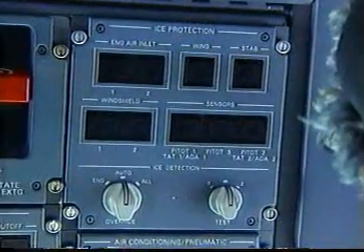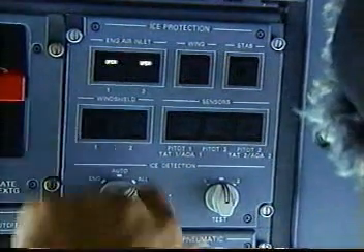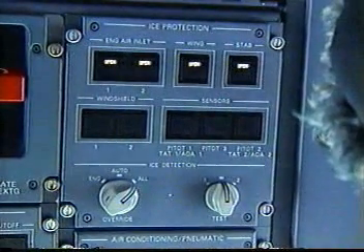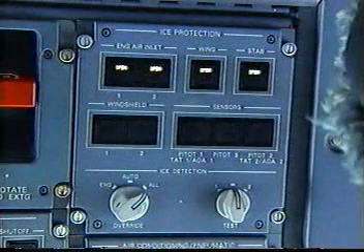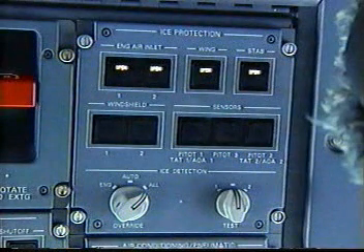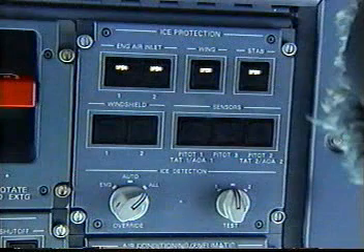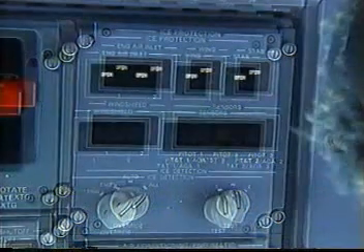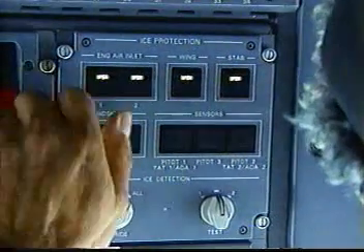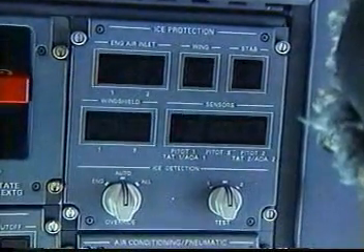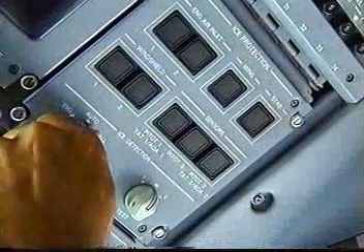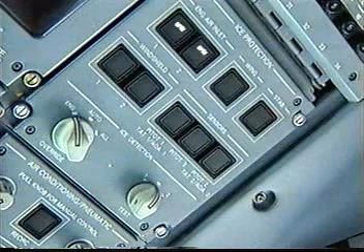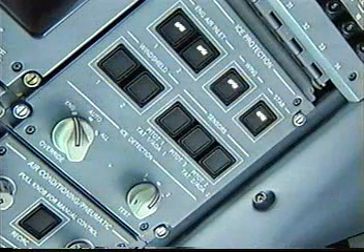The override switch, when selected to all, allows the flight crew to bypass the ice detectors and manually turn on all ice protection systems, provided that the airplane is airborne or wheel speed is above 25 knots on the ground. Selecting Auto allows automatic operation of the system. Selecting ENG turns on the engine anti-ice protection system and maintains the remaining system operating under automatic logic. A test knob to perform a system test is also included.